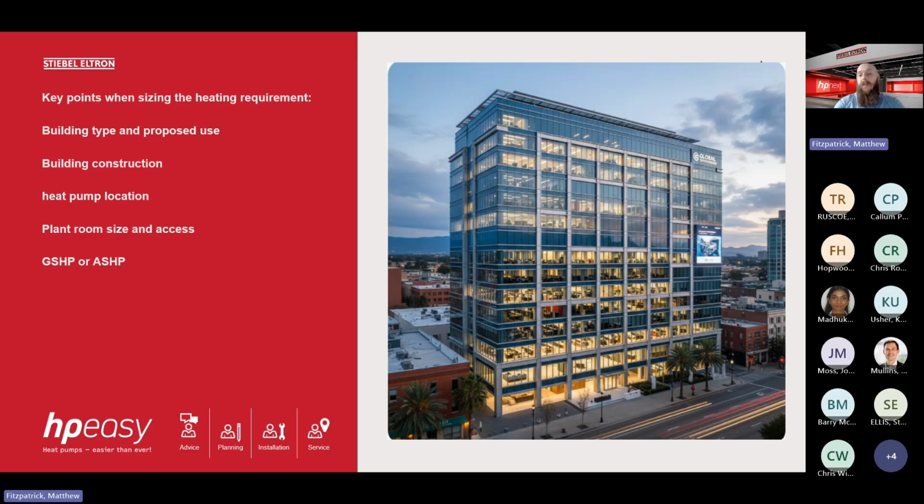If most of the building is solid wall, with or without insulation, it's relatively easy to complete a heat loss calculation. And I've purposely used an AI generated image on the slide we can see on the screen, because in most modern buildings, we want a light, airy, open feel, which normally means a large amount of glass. Now, glass has a higher heat loss than brick, concrete, all of the normal building materials that we use. But on the other aspect, it has a greater solar gain.